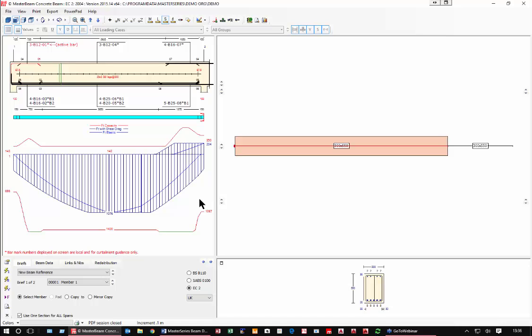In the Eurocode, the shear reinforcement, or the shearing on the beams, applies an additional drag on the tensile steel because of the truss action of your analysis using a truss model. But it does quite kindly say it can never be greater than the maximum, so that's why we get this capping off and not an increase in drag there, and likewise here.